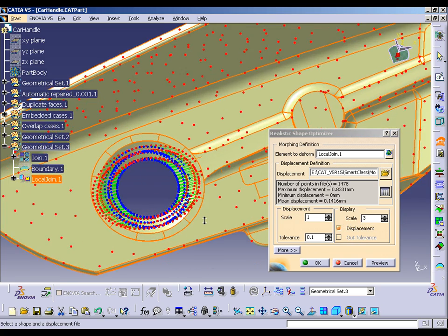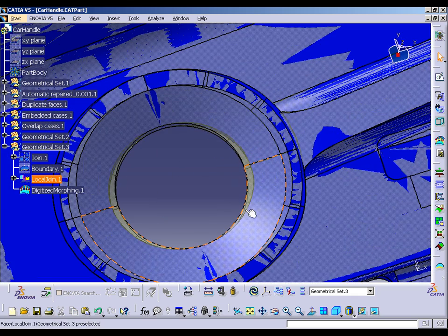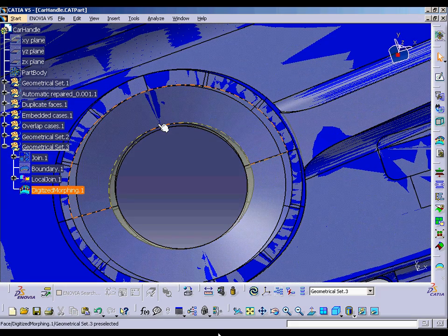The mold designer can visualize and compensate it by applying a counter deformation to the nominal part. The result is editable and can be refined by additional simulations if needed. The counter deformed part will be used to define the mold tool. The mold designer will therefore create a round tool in order to get the right molded part.